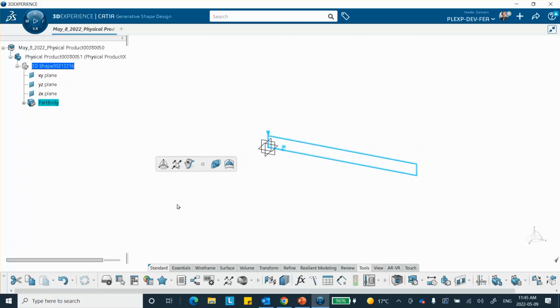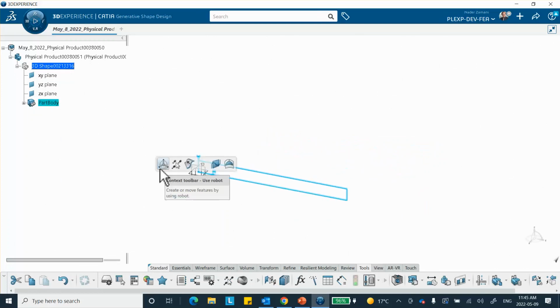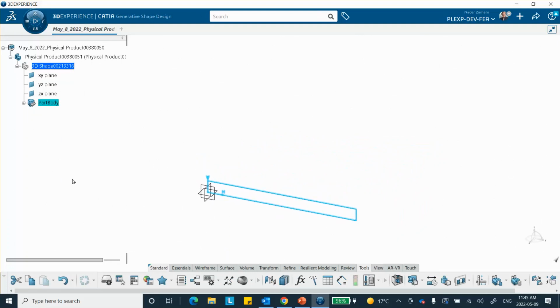Now it's a plane because we want to kind of compare these things with the fellow's ABAQUS calculation grossly. Okay. And he is doing it in plane strain condition. So what I need to do is to extrude this thing so that it's relatively long. So I think I'm going to extrude it by 20 millimeters.